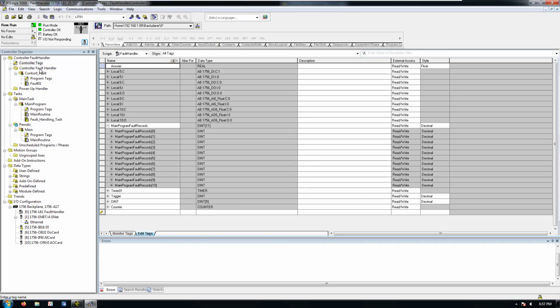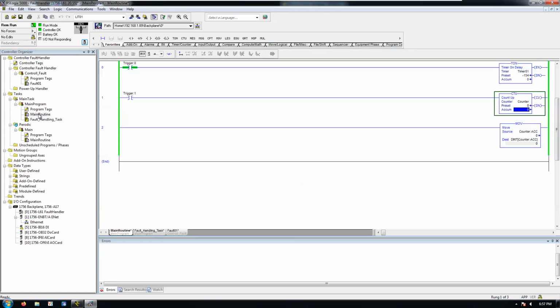Watchdog for another, like for the other periodic task. Or even this one, so I can trigger this. So we can write into the 5th value, no problem, or the 4th value. But once we get to actual 5 here, that doesn't exist. So we've got another fault condition.